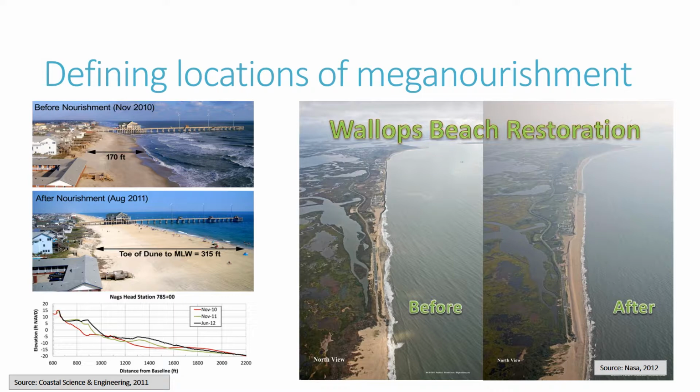It is important to define convenient locations for beach nourishment. The effectiveness of beach nourishment options depends on the location and on the external agents acting in the system. For example, waves, wind and tidal currents can resuspend sediments and transport them far away from the initial beach nourishment location. Optimum solutions can be found which maximise the transport of sediments in the desired location. This can be the location where the nourishment itself happened or nearby areas.